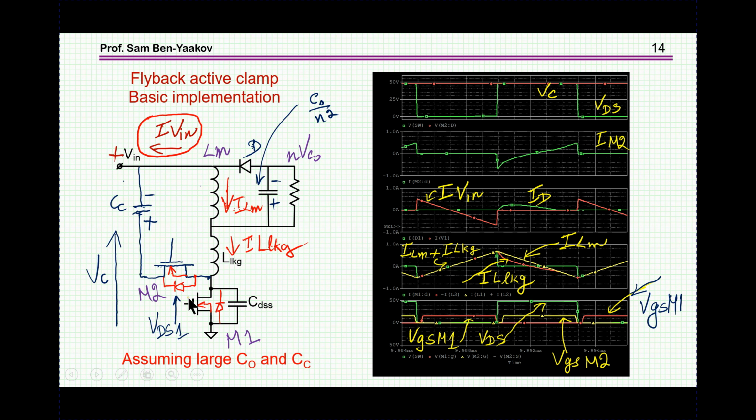And then we have an extra transistor. This transistor, we are actually using this built-in diode for the first instance, and in this case you see we have something like the RCD. This is the diode, this is the capacitor, except we don't have the resistor. The reason is that we are going to circulate back the energy, so we don't need to dissipate the energy by a resistor. So this is this auxiliary transistor which is put here.